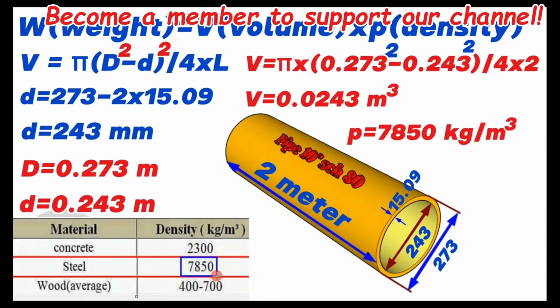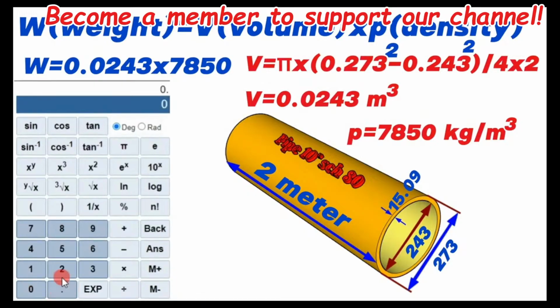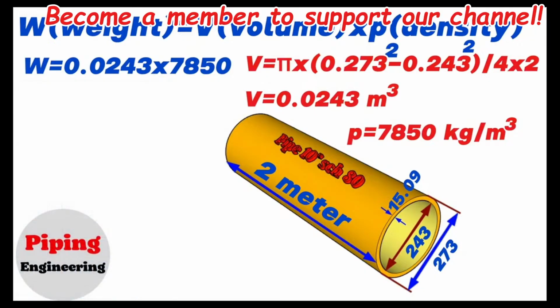Now let's write this information in the weight calculation formula. Weight equals volume 0.0243 cubic meters multiplied by the density of the material of the pipe, 7,850 kg per cubic meter. Using the calculator, we find that 0.0243 multiplied by 7,850 equals 190. So, we found that the weight of the 10-inch pipe in our example equals 190 kilograms.